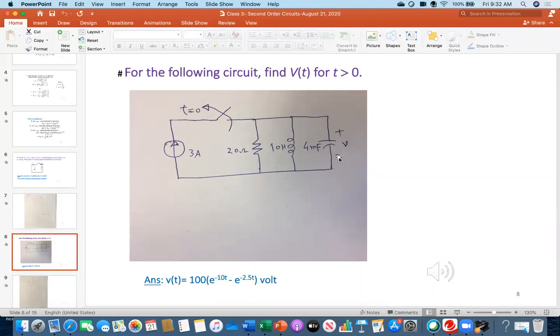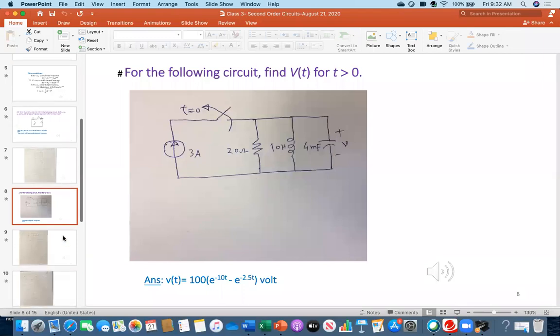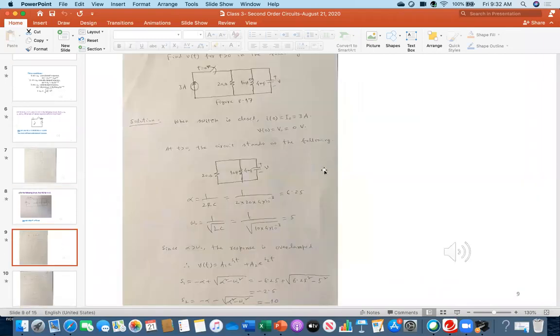And then what will be the voltage across the capacitor under that condition? 0 volts. Great. Yes, because although it is open, it is shorted. So this means it will appear as 0 voltage here. So those two are the initial conditions. Everybody see in the next slide.